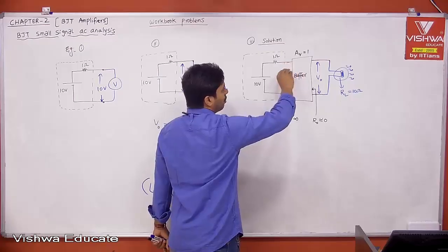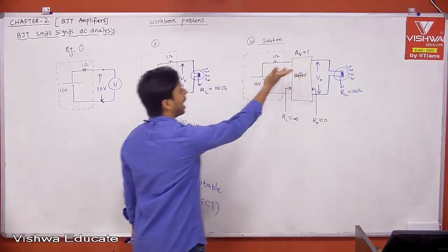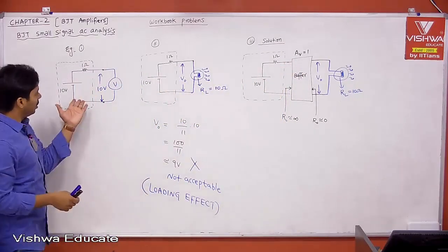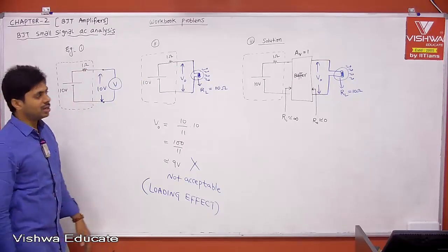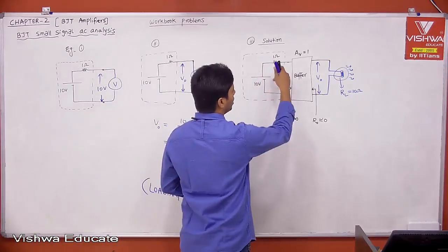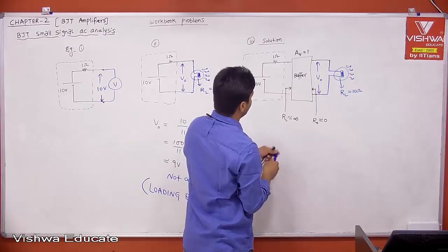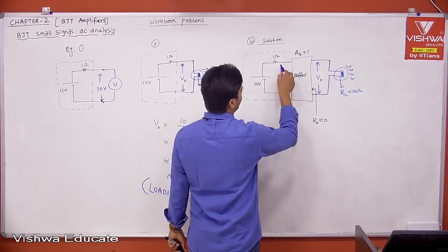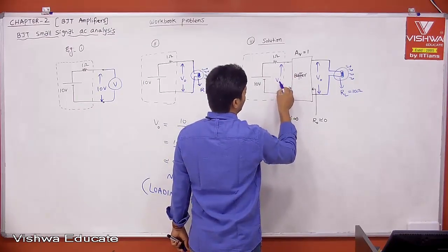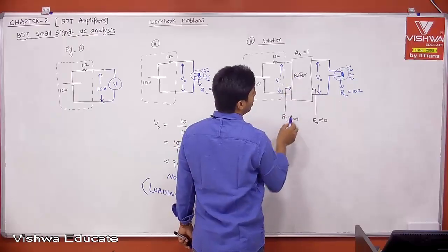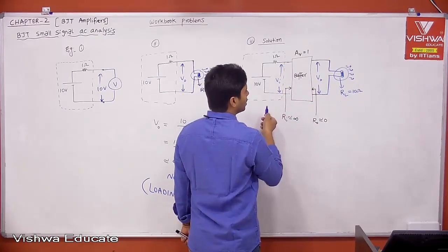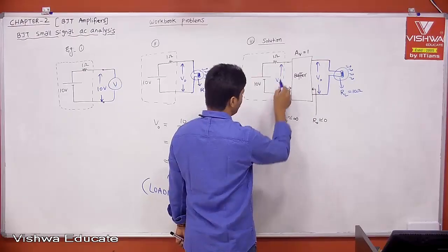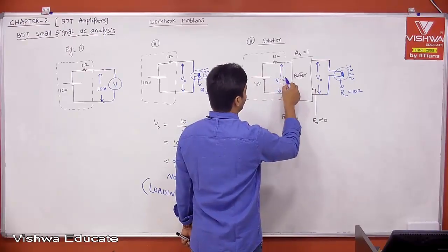If you treat this as an open circuit, then it is equivalent to an open terminal, measuring the open terminal voltage, right? Therefore, tell me what is the open terminal voltage? When I say VI, the input voltage to your buffer amplifier, and V0, the output voltage of the buffer amplifier, this is nothing but VI. Your VI is equal to 10 volts.